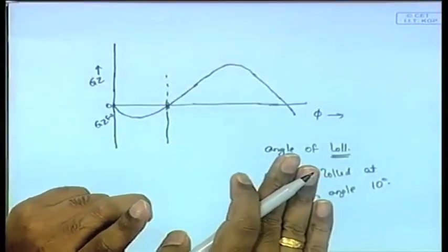If it heels more than the loll angle, it will come back to the loll angle. So, it will be like this. If it is like this also, it will be pushed back here. If it is like this also, it will be pushed back here, and finally it will go like this, most likely. I mean, with slight variation, a ship never goes upright, it always goes like this. Even if it is a good ship, it will never remain upright, it will always heel a little here and there. That is why we are doing all these calculations, but this ship will be in this position, it will heel like this. Okay, means its general mean motion is like this, that is the meaning. That is called lolling, that angle of loll it is called.